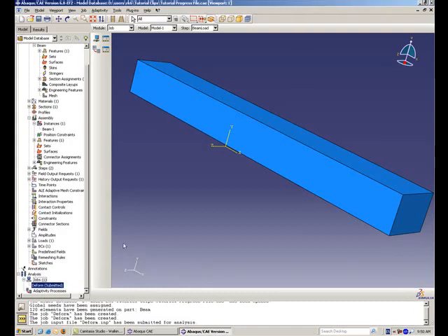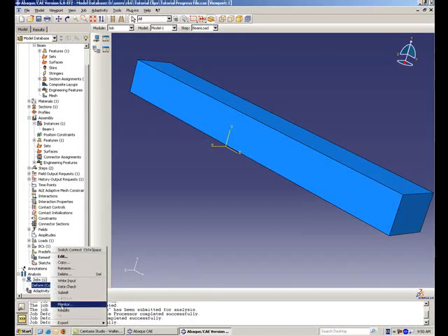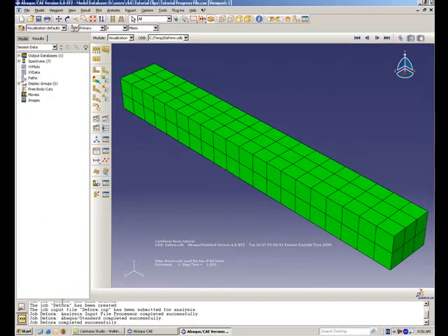The job says Submitted when the analysis input file is being generated, Running when Abaqus analyzes the model, and Completed when analysis is complete. When the status says Completed, right-click on Deform and select Results to enter the Visualization module.